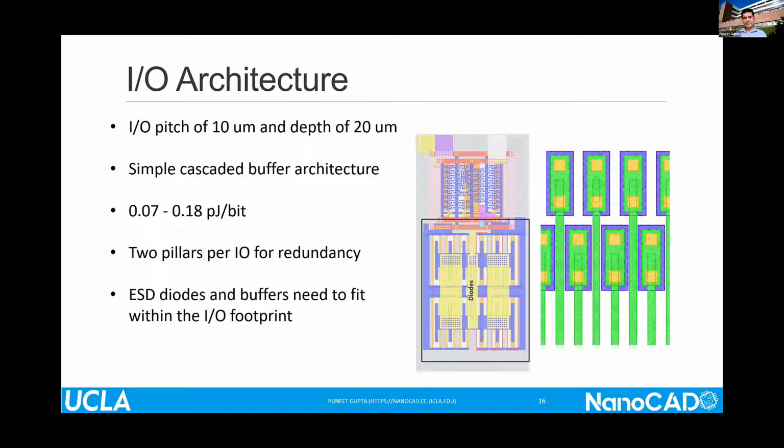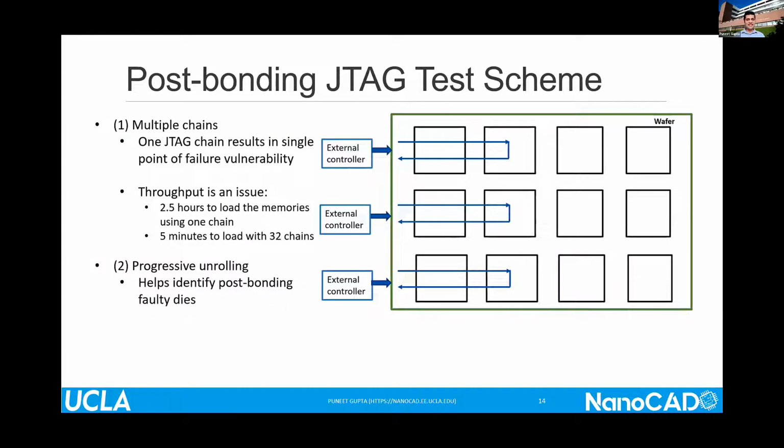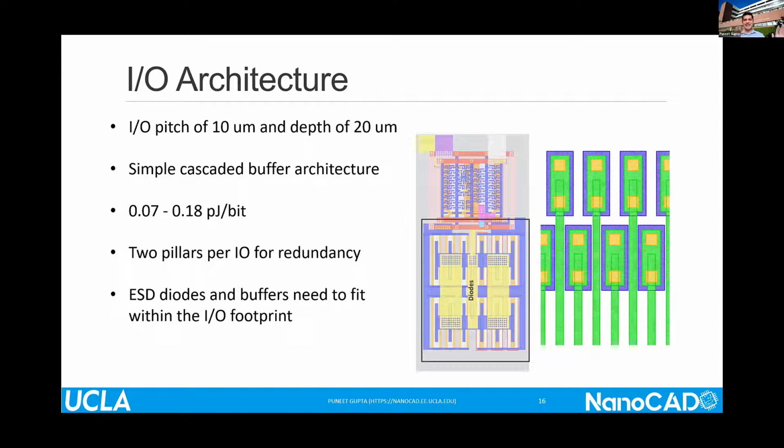Yeah, I can imagine. And then last question, how did you test high-speed IO interconnects? Is there any DFT to test it? Our high-speed I/O is not SerDes. That's what I keep emphasizing. These are simple cascaded buffer links. These are buffers here, buffers there, just like what you have on any modern digital SoC. That's it. All they need to drive is 300 microns of copper wiring plus some small amount of ESD cap. Got it. So testing this is nowhere near as difficult as a serialized link.